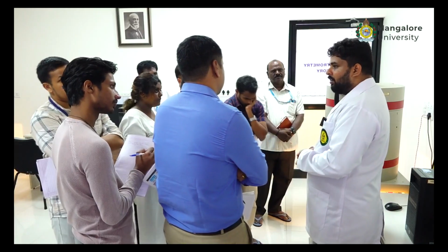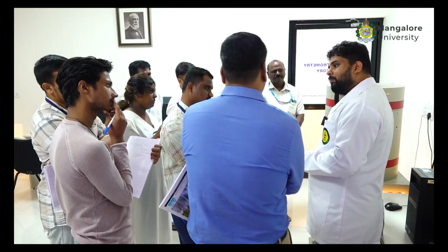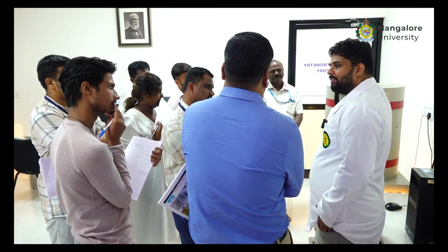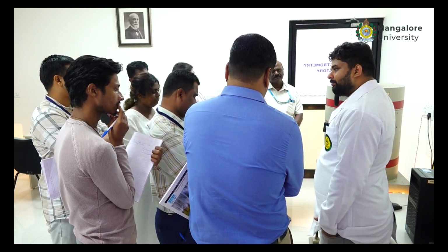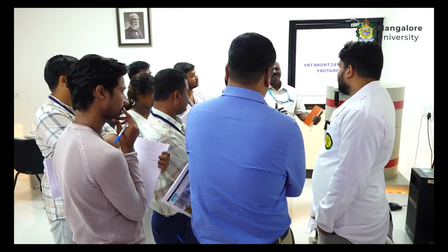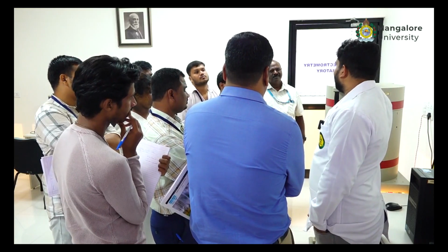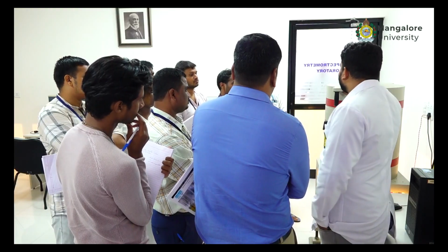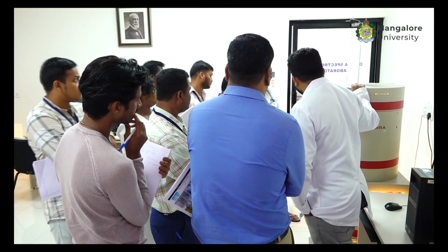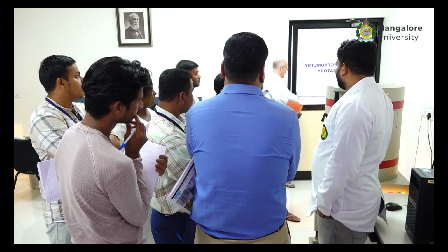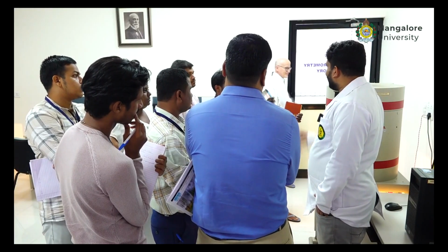Now, can you tell me the rationale behind keeping this detector immersed in liquid nitrogen? With the information you have got now. Maintain the temperature. Why should I maintain the temperature, sir? Create a depletion region? No. Yes, sir, the temperature increase actually increases the noise.